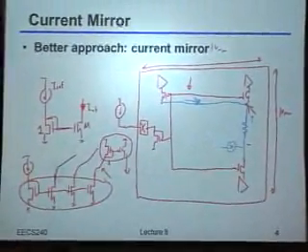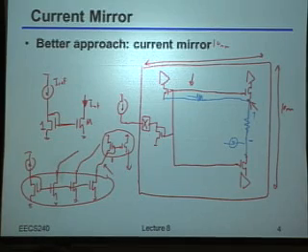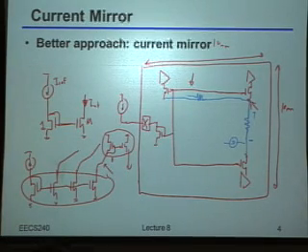Because basically in both cases, what you really care about most is how sensitive the receiving transistors are to changes in the potential on that wire. Now, obviously, if you have a very small current, then if you couple any sort of transient signal into it, or rather to say it a different way, if the impedance of that wire is very high, and you couple some charge into it, that will translate into a larger relative change at the output. But if you're really going to do things right, you probably don't just route that wire, bare, on top of all of the digital things or all of the noisy things that could possibly be in the world.